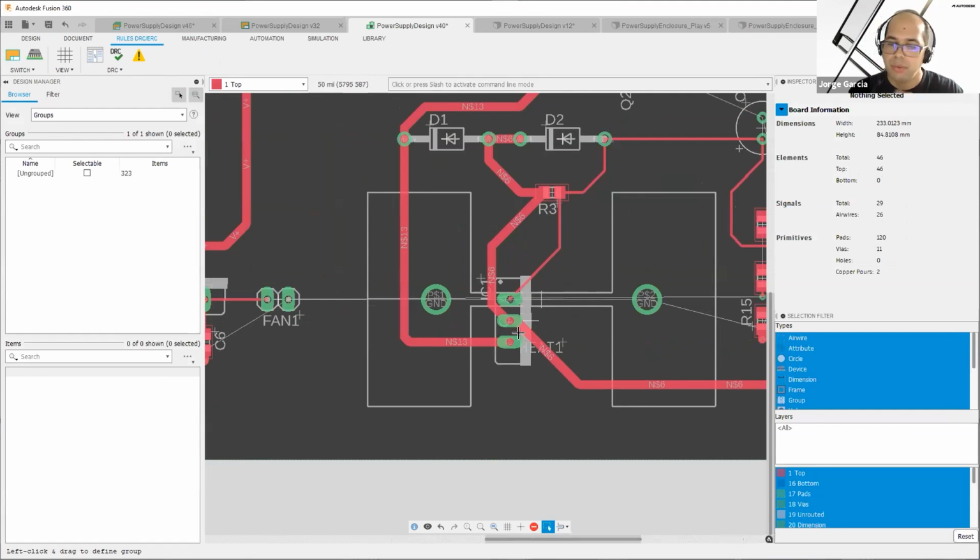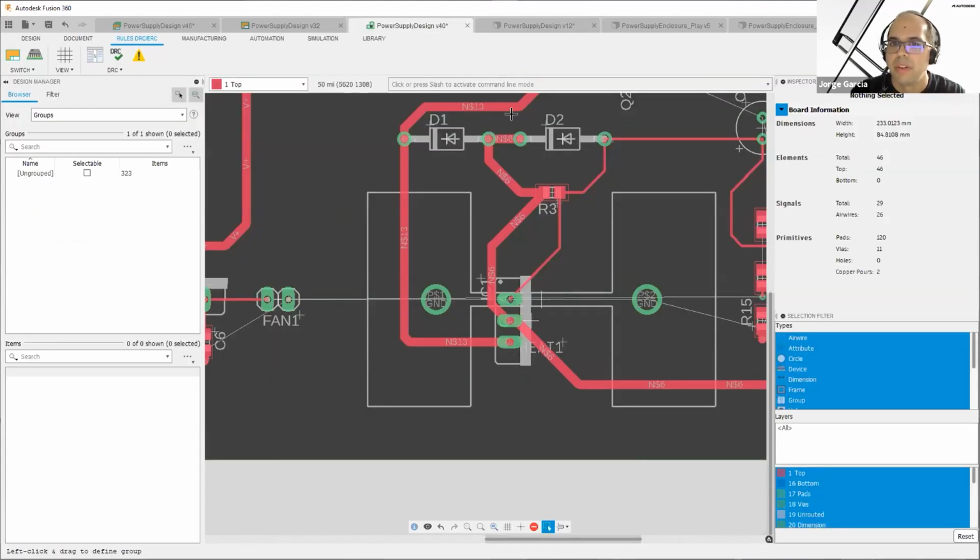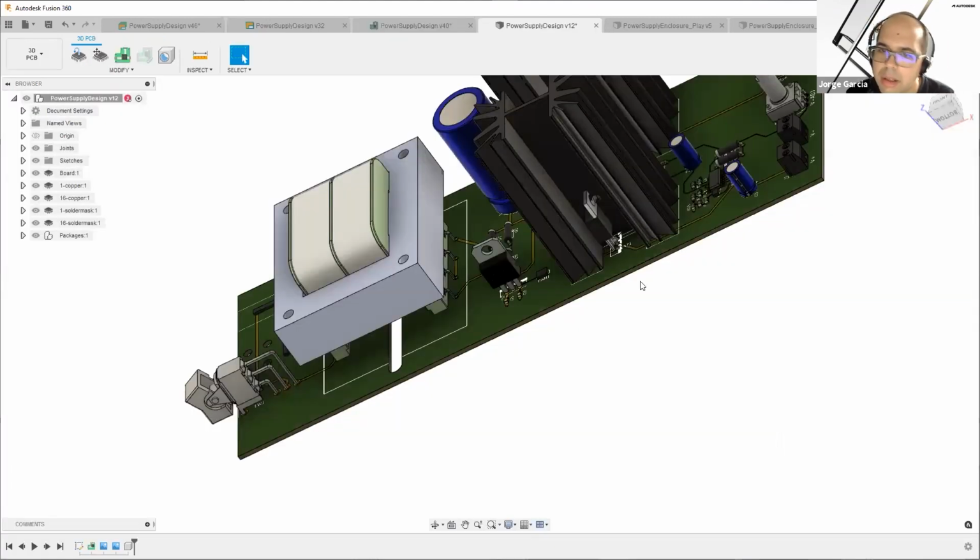And this is something that's unique to Fusion 360. So I could actually right here just finish the move, finish making the rotation, and then have it reroute again. But I think the concept is demonstrated. You have something here, you can just fix it, and then it will automatically try to reroute everything on the 2D PCB, to keep everything in sync and in a reasonable state.